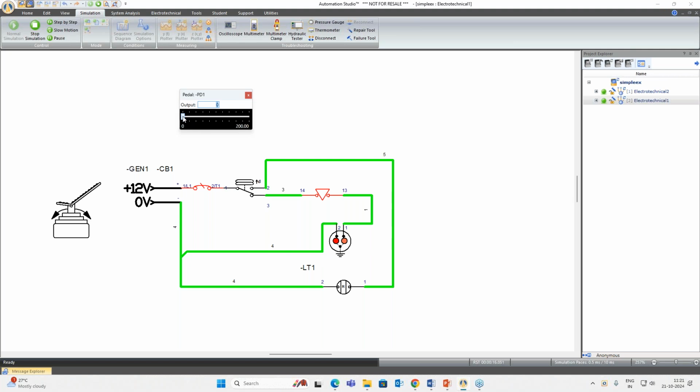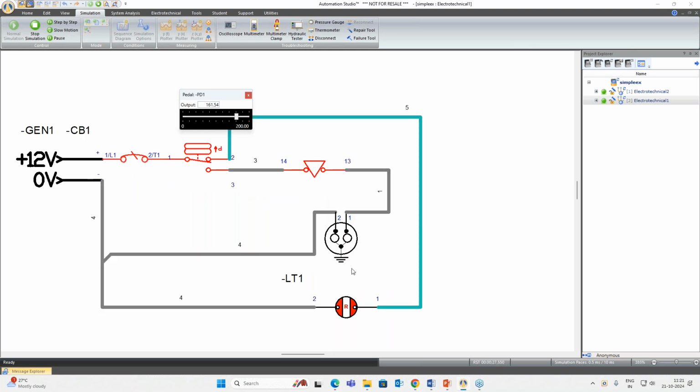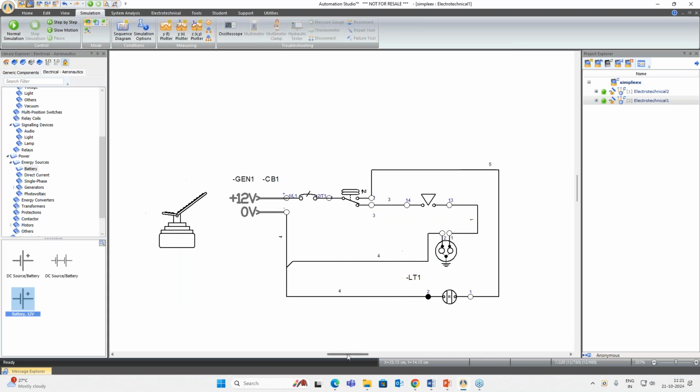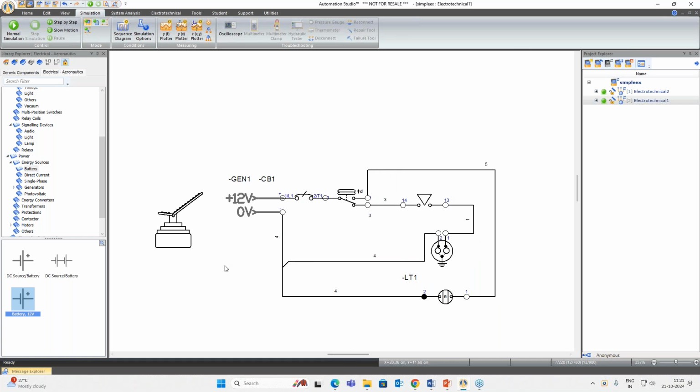But now I change the assigned pressure to more than 100. It should change the position, and you can see this is now activated, and this red lamp is getting activated, meaning it is showing the status of that signal. So if pressure is more, it means that my plane is at the up position, so this LED is giving me that status. And if my pressure is low, it is showing me the plane position as a down position. We can correlate with that scenario.